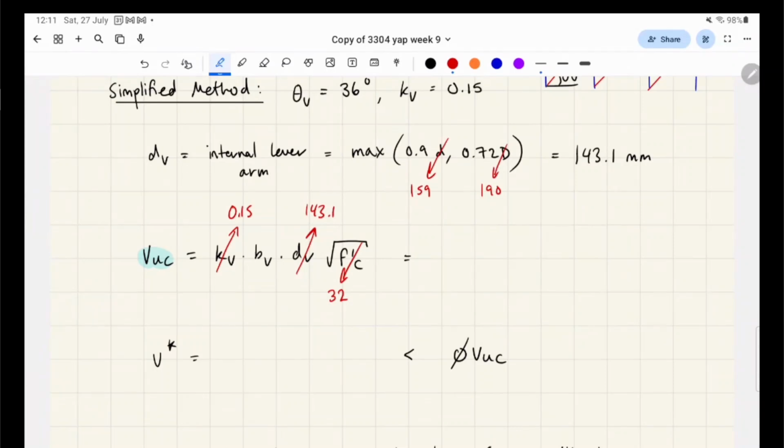All right. So BV is the shear width, right? Basically, it's different for a T-beam. For a T-beam, BV is the minimum between the width of the flange and the width of the web. I guess this is unrelated to this question, but which one would govern here? The flange, no? The flange would be the bigger one. Oh, web, yeah, sorry. My bad. All good.